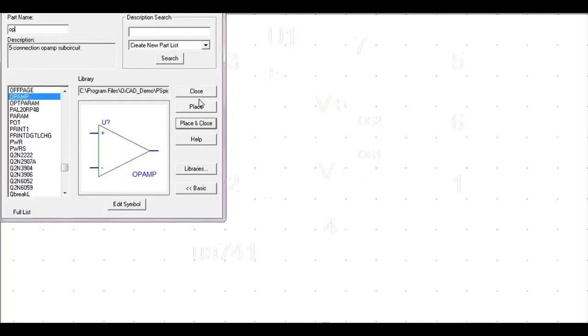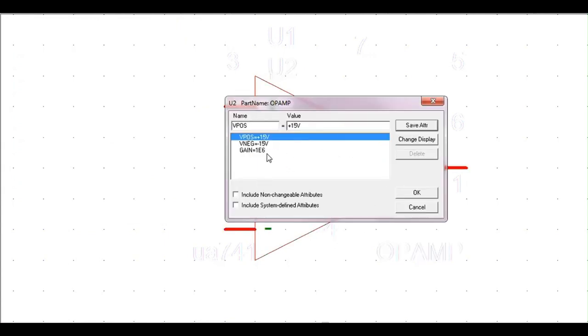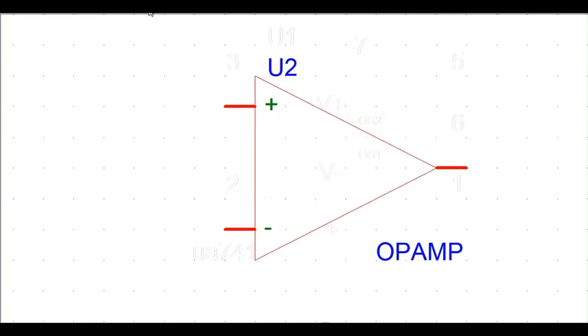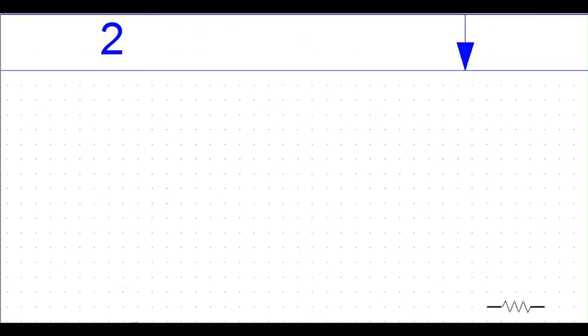So let's give that, and after that we can search for resistors. Basically we need a set of resistors. So first you can see I'm giving resistors, and you can see the names already given here, R1, R2 and such. So let's give all the resistors. You can search resistors in place, which is basically on top, and I'm going to place all the resistors, and see we have 7 resistors here, and let's connect,